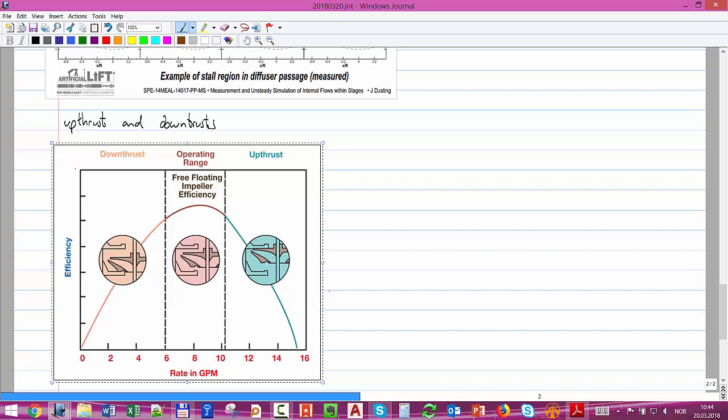If you fix it to the axis and keep it exactly here, it's another type of pump, and a more time-consuming operation. Then, if the temperature changes, you also have thermal expansion, and you might have contact. So it depends. But besides the efficiency issue, in floating type ESPs this is also a big problem that you have to take into account.